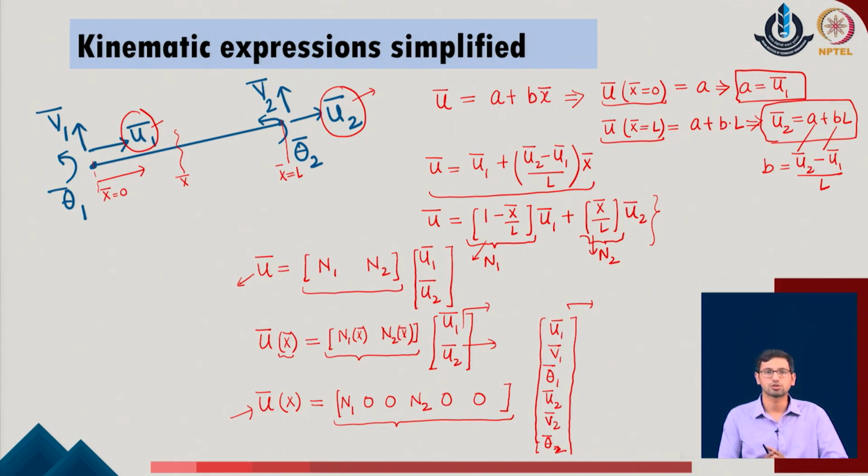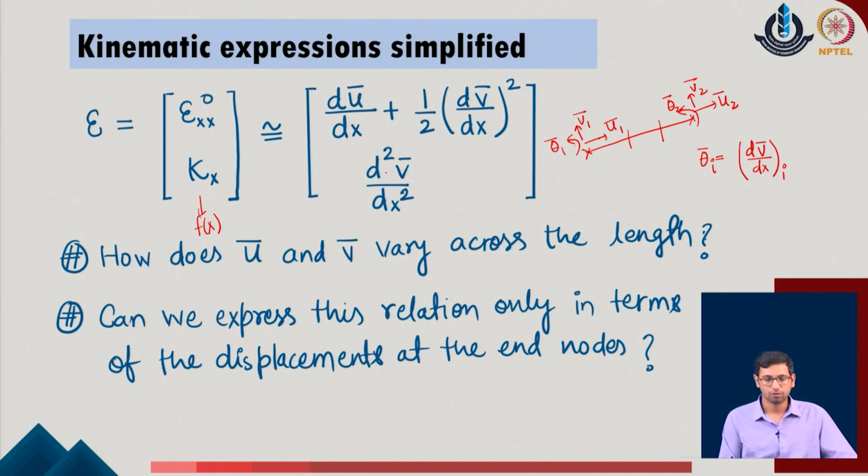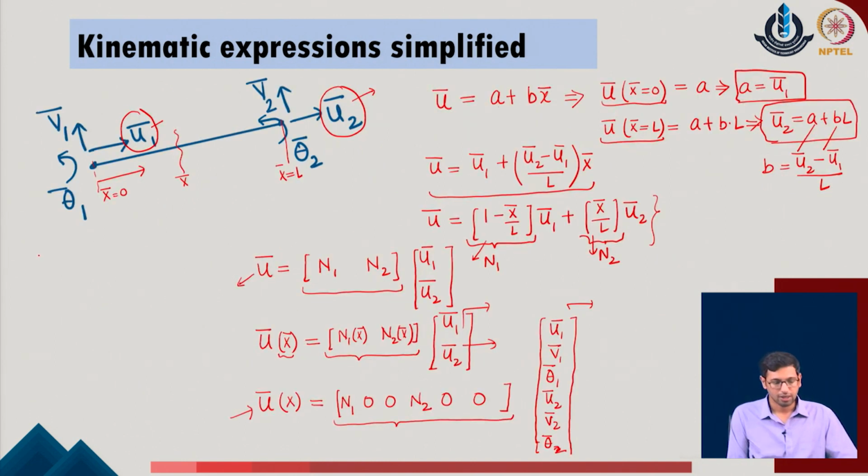So, the nodal displacement values which we were initially looking for can now easily be expressed in terms of the standard shape function parameter and the vector containing the nodal values of the given system. So, if you go back to the expression which we initially started with, wherever the du bar upon dx appears, I can simply bring this idea over here.